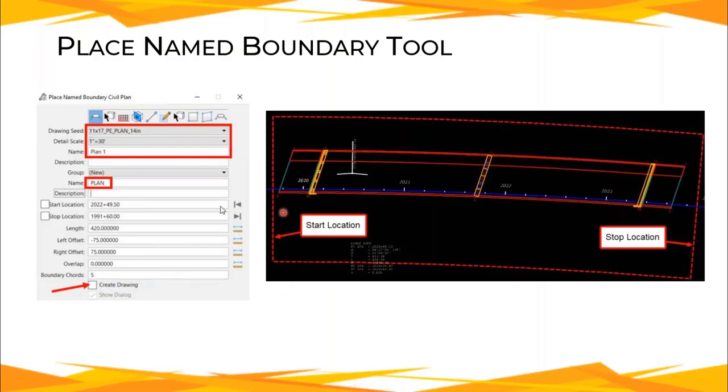And then when you're first setting this up, once you get all these settings the way you want, you can click on the alignments wherever you want the boundary to start. And then as you move your cursor ahead, this boundary will show up and appear here. And if I had zoomed out, and if I had a lot more boundaries I wanted to create, I can keep moving my cursor to the right, and it'll keep on creating those boundaries automatically. If I pull my cursor back to the left, it'll only have this one boundary created here.